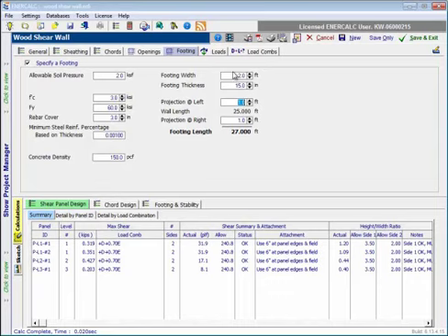So just keep that in mind, because you'll want to make sure that you don't specify something that's so long and so thin that that assumption is invalid. We're basically looking at long but thin or relatively narrow footings here, where the primary design consideration would be the flexure and the shear in the projections themselves, not such that there's transverse flexure.